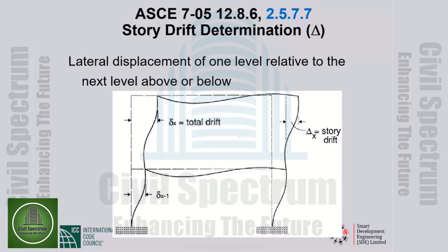Once, when we introduce an importance factor larger than 1 in the design of higher occupancy category structures, and the second time when we do a drift check, the purpose of which is to make sure that non-structural components are not damaged because of too much interstory drift.